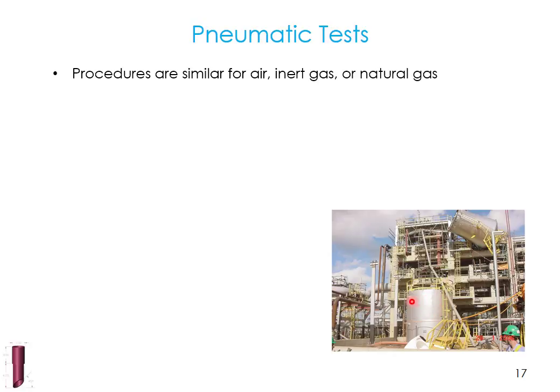This vessel pressured up to just a few pounds and put an up force on this top part of the vessel big enough to launch it up in the air, have it come down head first, top first. So it probably went a ways in the air. But this is not a pneumatic test failure. This is a horribly designed pneumatic test that failed uninvolved equipment.